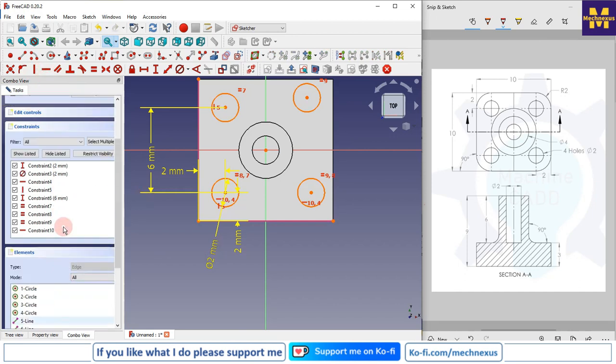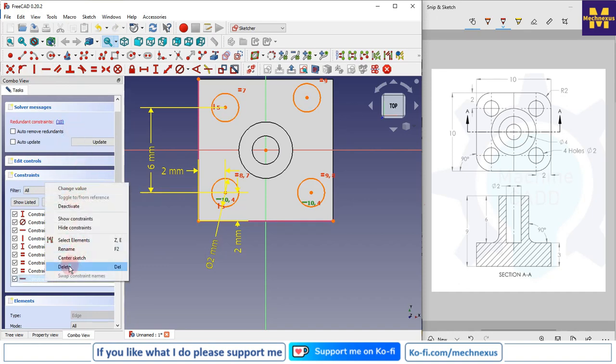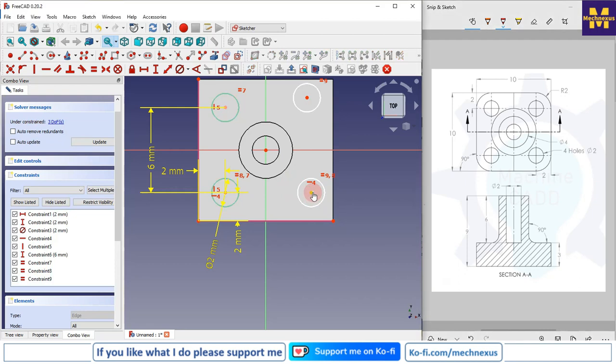Okay, some constraint is conflicting, so let's identify it. I will select the circle and move it. It is already horizontal, that's why we are facing the problem. Now all I need to give is the dimension between center to center, which is 6 mm. It is still not fully constrained, so I will select this one and this one and give vertical. In the same way I select this and this and give horizontal.